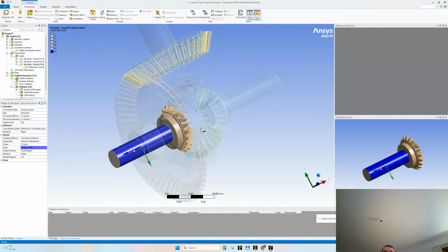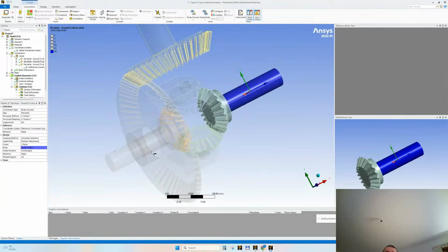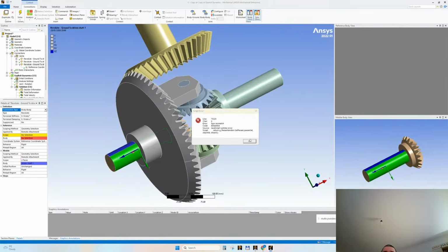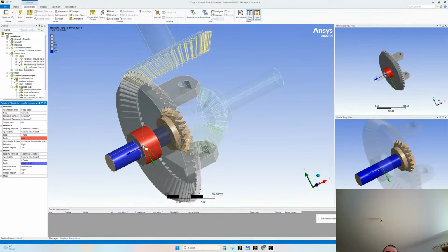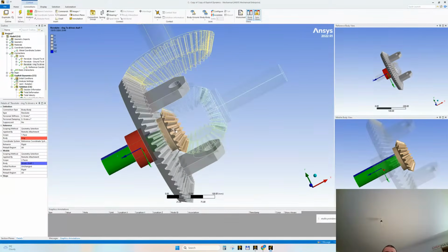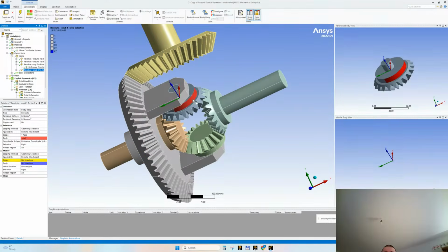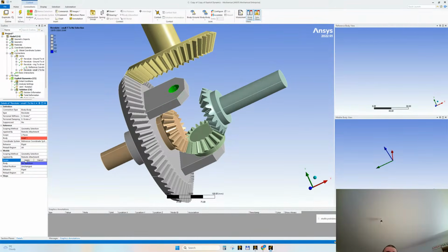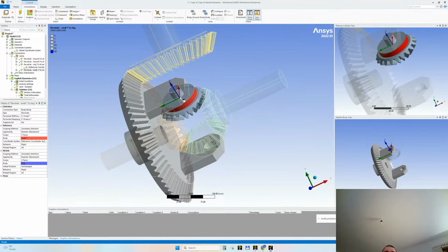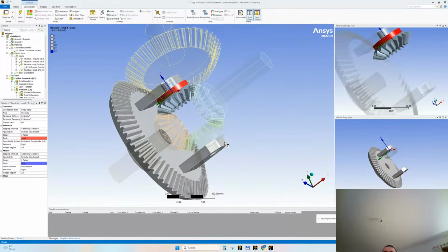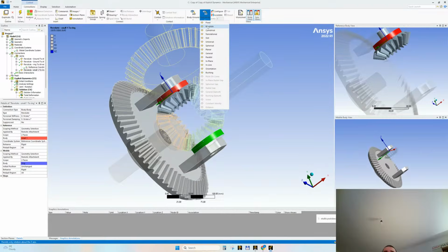This joint can be, you know what? Because we have a contact between this and this, let's make this joint body-body. We have this for one side, and let's have this for the other side. So we'll have the joint between these two. This is regarding this gear, all right? So this gear should have body-body with, let's also select this face, even though maybe it's redundant. We hide it with F9. Click these faces, apply. So right click, show all. We have this joint here. And also we do the same here, yes. Body-body, Revolute.